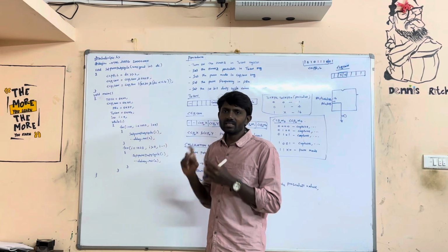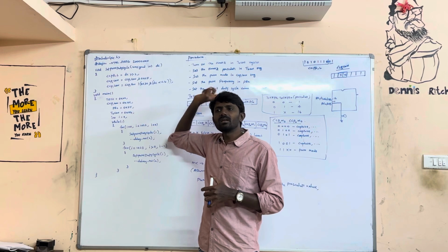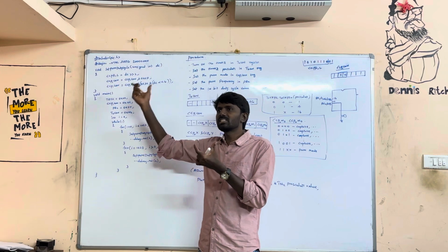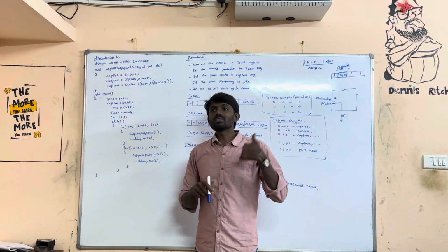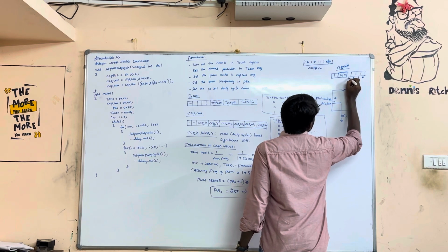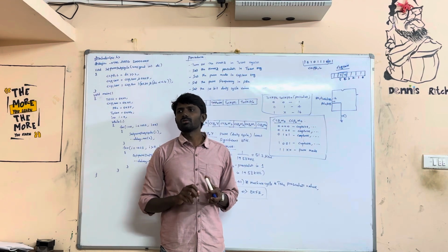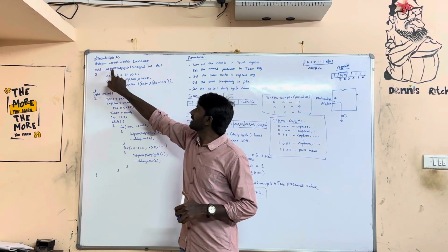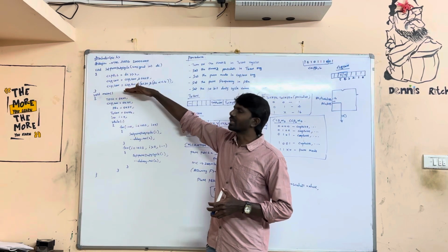So this function, some 10-bit number is coming. The 10-bit number you are putting in those 2 registers. The upper bits, from 3rd bit to 10th bit, you are putting in CCPR1L, and the first 2 bits you are putting in the CCP1CON 4th and 5th place. 0, 1, 2, 3, 4, 5. 4th and 5th place you are going to put those 2 bits. That's all. That is the purpose of using this function: set PWM duty cycle in the appropriate registers. Is everybody clear with the function?